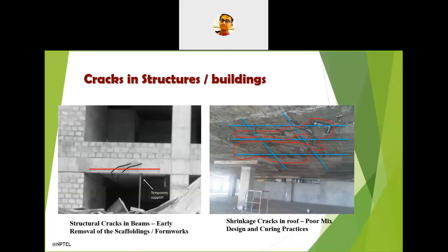So obviously there is a passage, there is a crack in between. There is a crack in the sense there is a passage through which the moisture is coming out and accumulating on the surface of the concrete, forming scales. Now you imagine that blue color lines as reinforcing bars. So obviously these bars will very soon suffer from different types of corrosion.